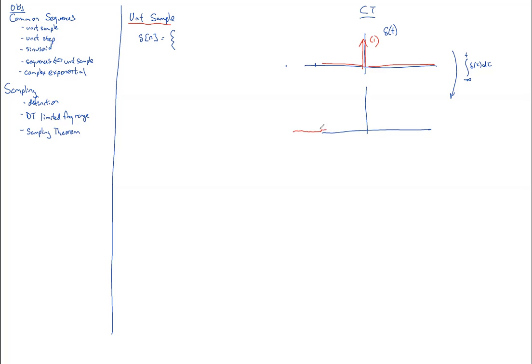0. Okay. And then what happens just as we pass this 0 point? What's our area from negative infinity to 0 plus? It's 1. Right. And then as we continue on, it's the same. So my question is, Gordon, why don't you finish up? What's the integral of an impulse in continuous time? It's the unit step.